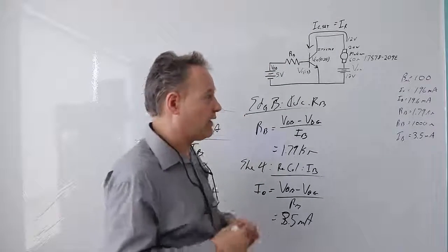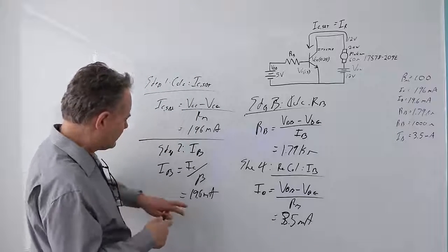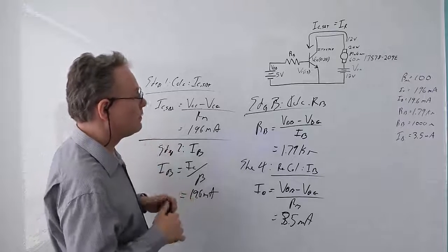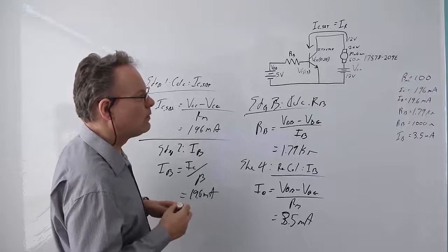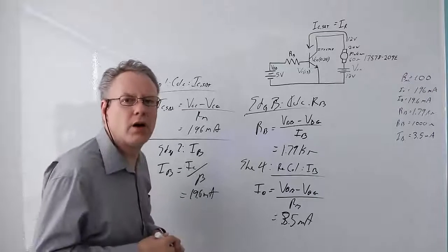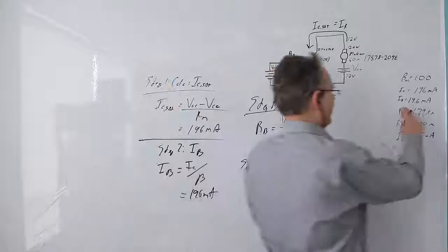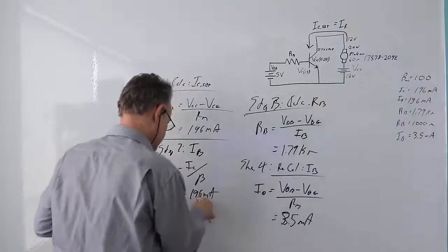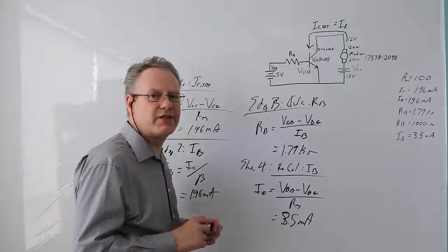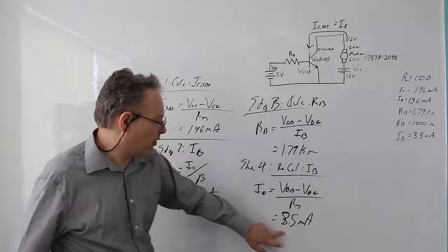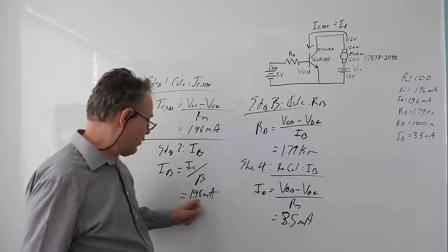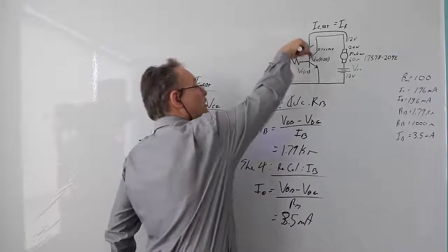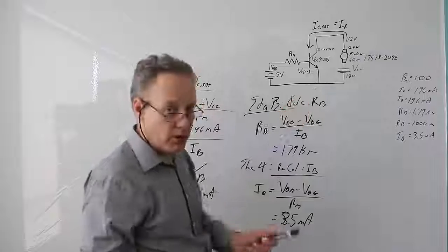and I know that I need at least 1.96 milliamps. We just did something funky. I moved my decimal wrong. Let's go back. Here we go. Okay, now that makes sense. All right. So 3.5 milliamps is a lot bigger than 1.96 milliamps. So I'm good. It's absolutely giving enough current through the base to saturate that, and that motor will be on.